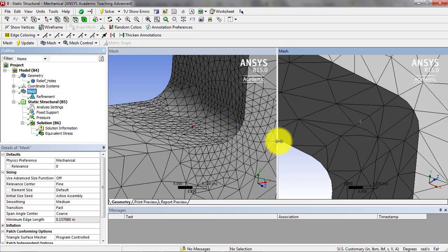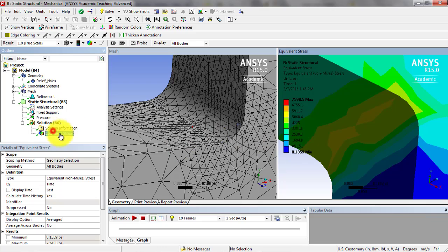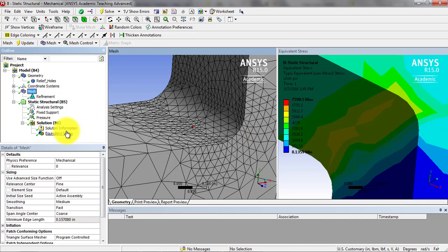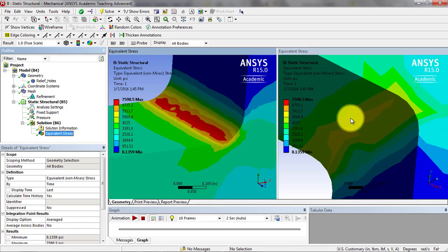Not just here because our license is limited, because we can only do 256,000 nodes or elements. But any time you're doing computational analysis, you want the thing to run as fast as it can, so you can do as many models and different iterations and solve things quickly. And so when we do the mesh refinement, we want to do it in areas where there's high gradients, where things are suddenly changing. So in this case, actually both cases here, we had sudden changes. Like see the yellow out to green changes very rapidly.